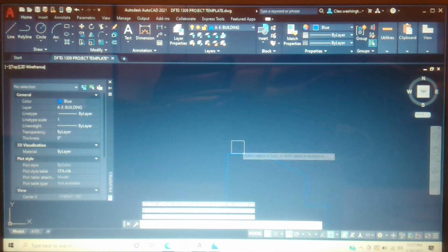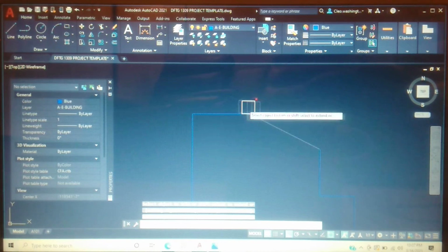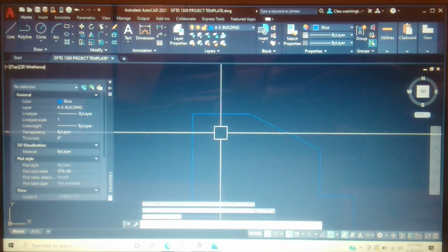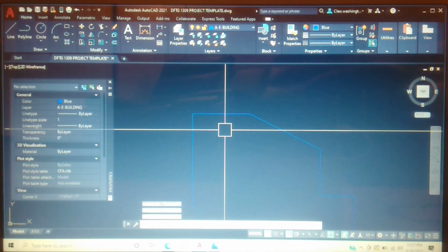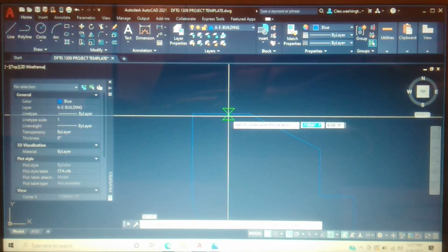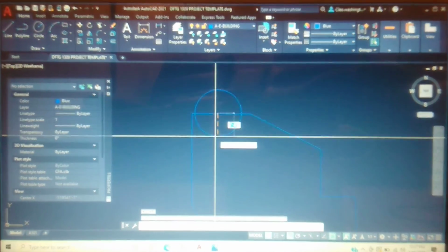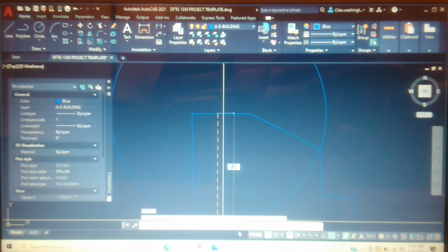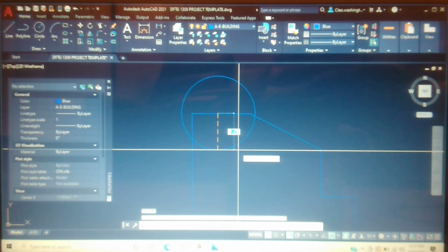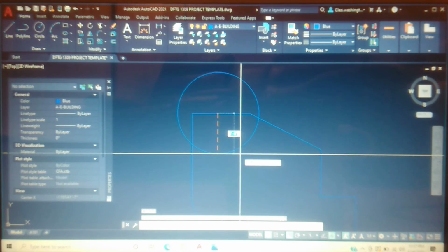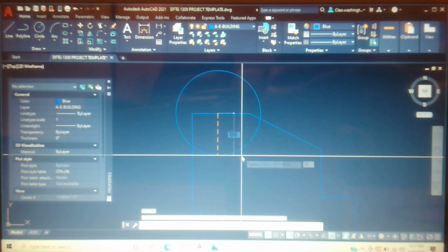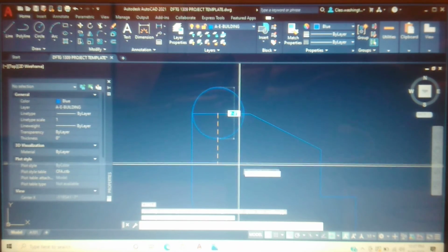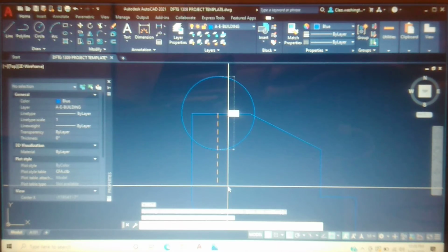Okay, so now actually I should have done something different, but we'll make an adjustment because things like this will happen. So this is good for y'all. Let's go ahead and draw a circle, and let's snap to the center line. And you want to hit, see where it says D right here for diameter? Right now it's automatically set to radius. We want a diameter of 4, so you hit D, hit enter, and then type in 4 foot, enter.